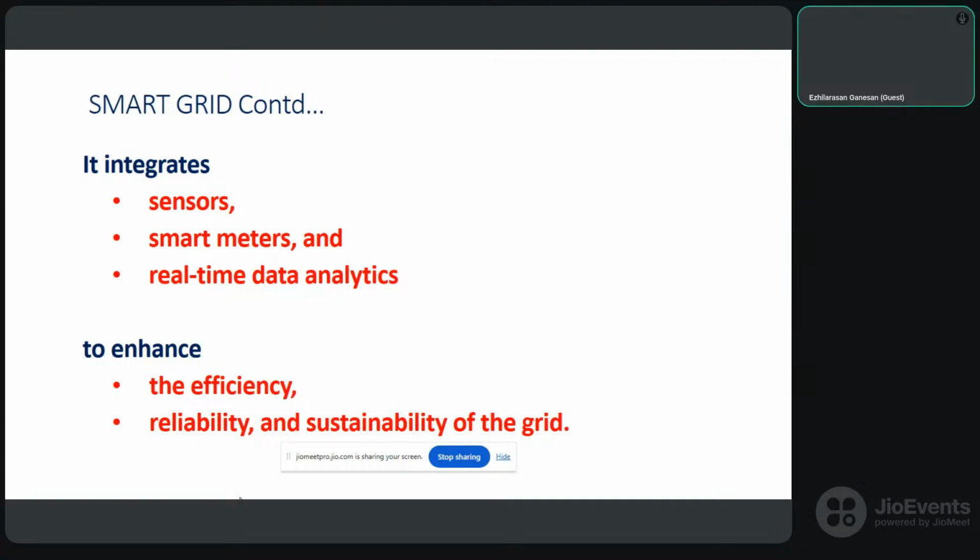Right. The first thing displayed is the date and time. Then kilowatt hour, that is the unit of electricity. Then voltage in each phase of supply. In all houses now it is three-phase supply. In each phase, what is the voltage, and in each phase what is the current. What is the active power drawn, what is the reactive power drawn, what is the demand, and power factor. See how many parameters. Is it not an improvement of technology? We are getting a lot of inputs from a simple meter in your house. You have to appreciate that. This enhances the efficiency, reliability and sustainability of the grid.